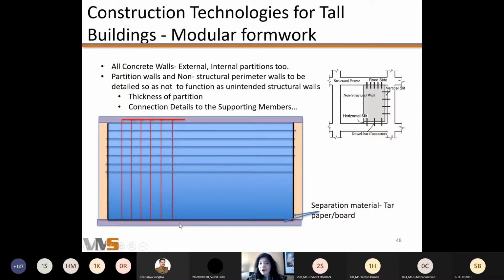But here, for all practical purposes, I just give like a 10-20 kind of anchorage into the lower element. Likewise on these sides also, I just give the bare minimum, 50 or some such thing. So basically these are walls which are, for practical purposes, hanging, but of course they are anchored for 10-15. In case of a very large earthquake or something, obviously this is going to disengage.